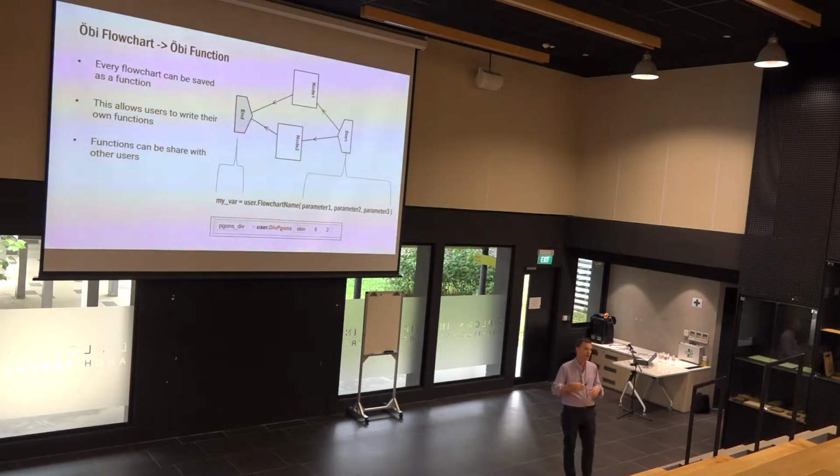So let's say in a normal CAD system, you have a function to draw a polygon, and you have a function to draw a line, but you may not have a function to draw a window. If it's a BIM tool, you would, but let's say it's a model you make, and there's no tool for it, then you can make your own tool. You can make your own flowchart that does it, save the flowchart as a function, and then add it to Mobius.